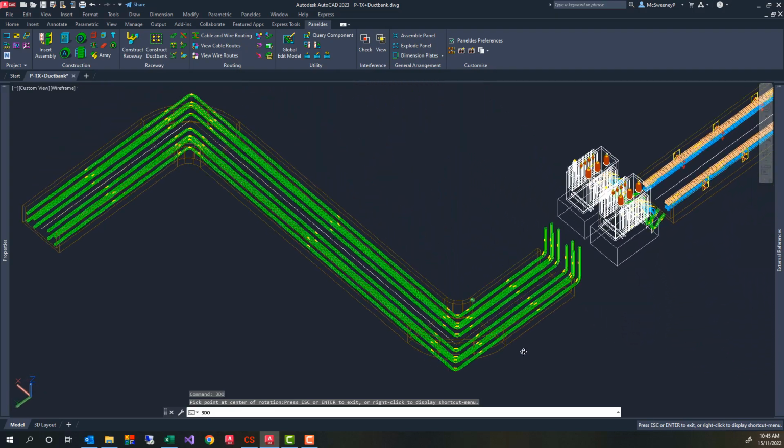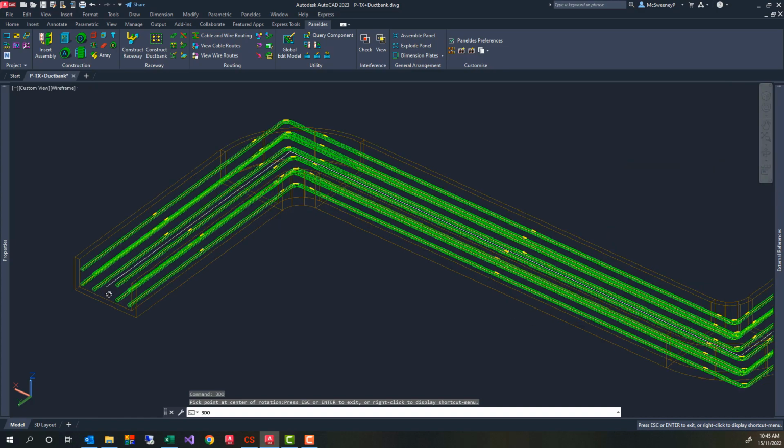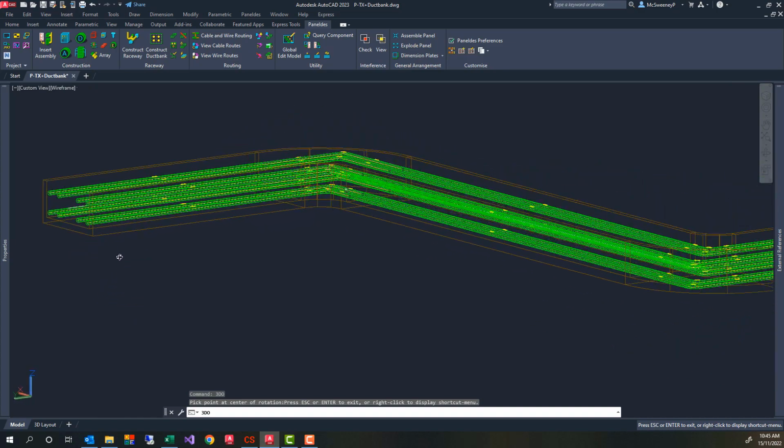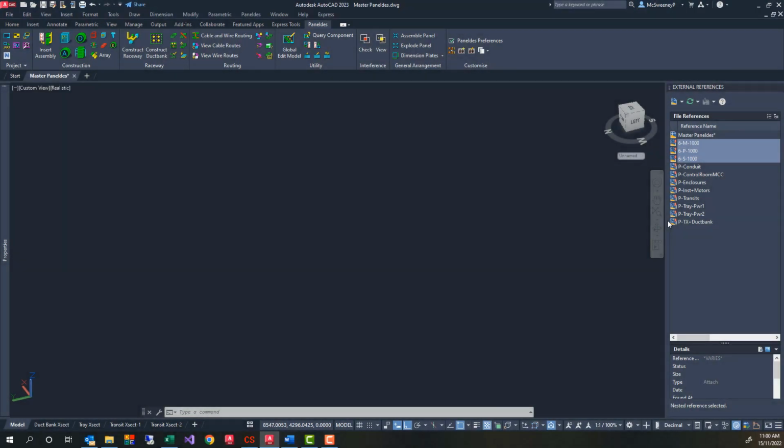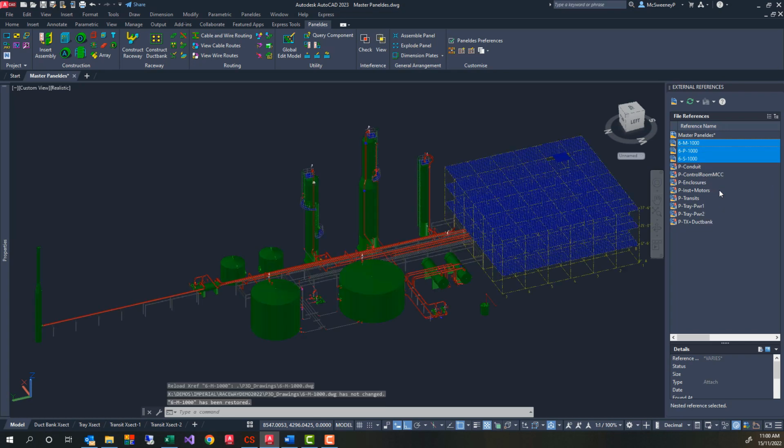To recap, the duct bank editor provides a fast and efficient method of creating underground conduit arrays or road crossings. As mentioned during Raceway construction, it is very important to avoid CAD slowing down and to construct without screen clutter, making your snaps difficult. One of the best methods to achieve this is to subdivide your electrical model into many XREFs.